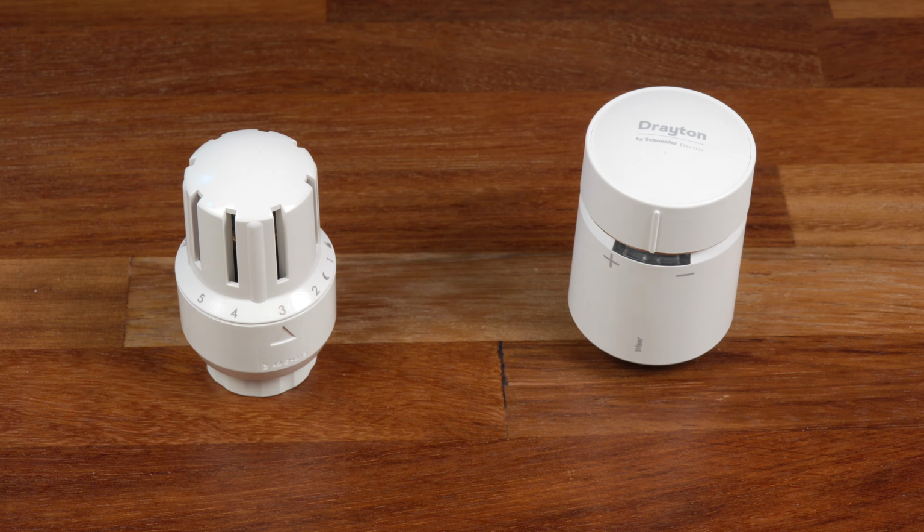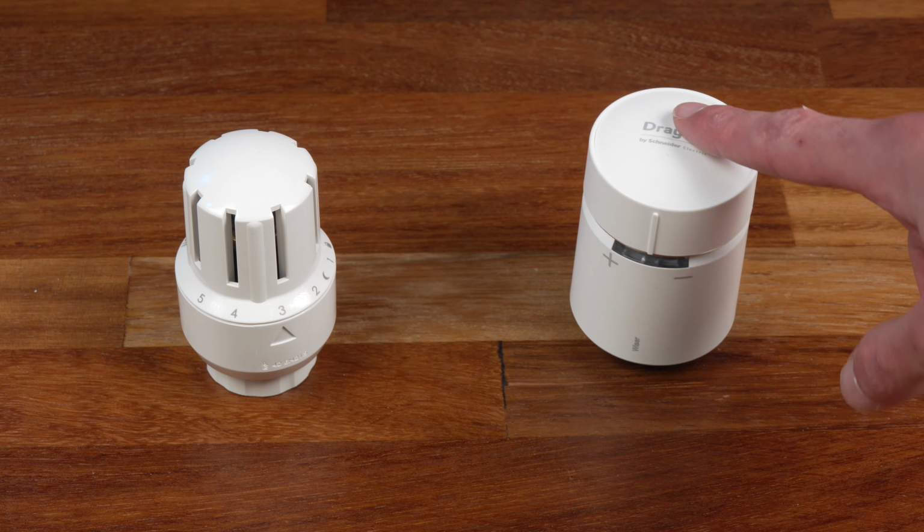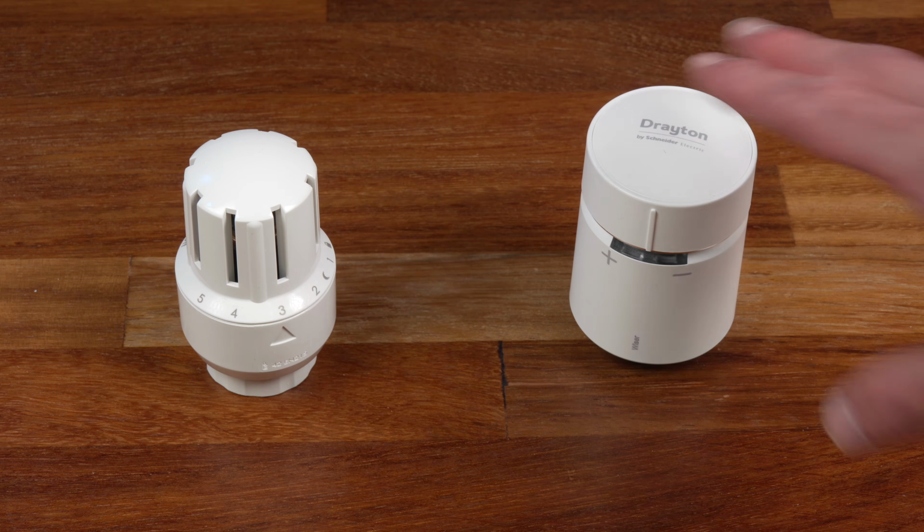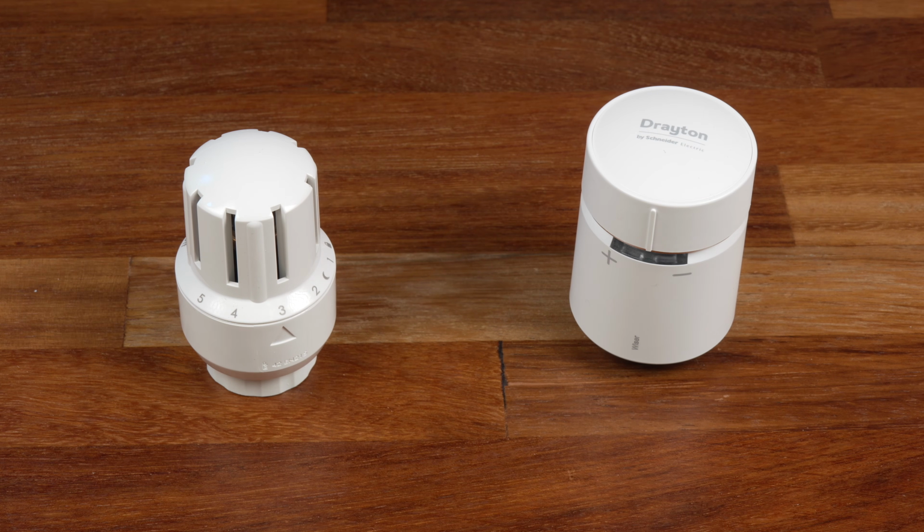Because these are connected back to the Wiser system, like a normal TRV, once the room temperature gets beyond the thermostat set point, these will start to close off flow to the radiator and turn the radiator off. However, if the room then gets too cold, these smart valves can also turn your boiler on. That means that not only can the TRV set a maximum temperature for a room, it can also set the minimum temperature of the room. And the other benefit of these smart TRVs is that you can change the temperature in each room directly from the app or on a timer.